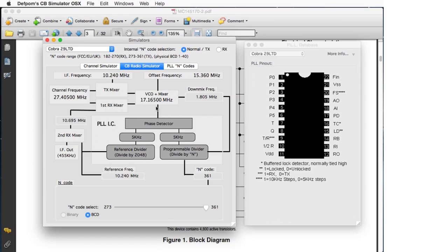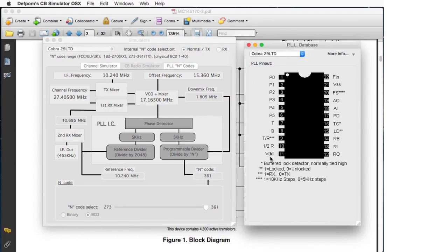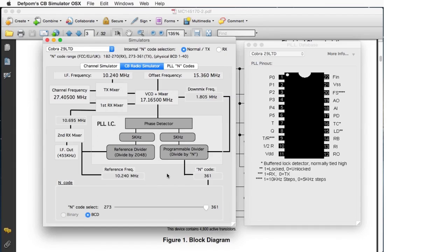So this voltage here, when it's locked, will be somewhere in between the PLL's supply voltages. So 0 volts and whatever the supply voltage might be, right? This one here is VDD. Usually that's 5 volts on this particular PLL. But you also have to allow for the fact that it doesn't go rail to rail, so it doesn't go fully to 5 volts. It's got a gap in what it can actually supply. So I think it's about 4.6 is the absolute upper limit of what this PLL can put out for a